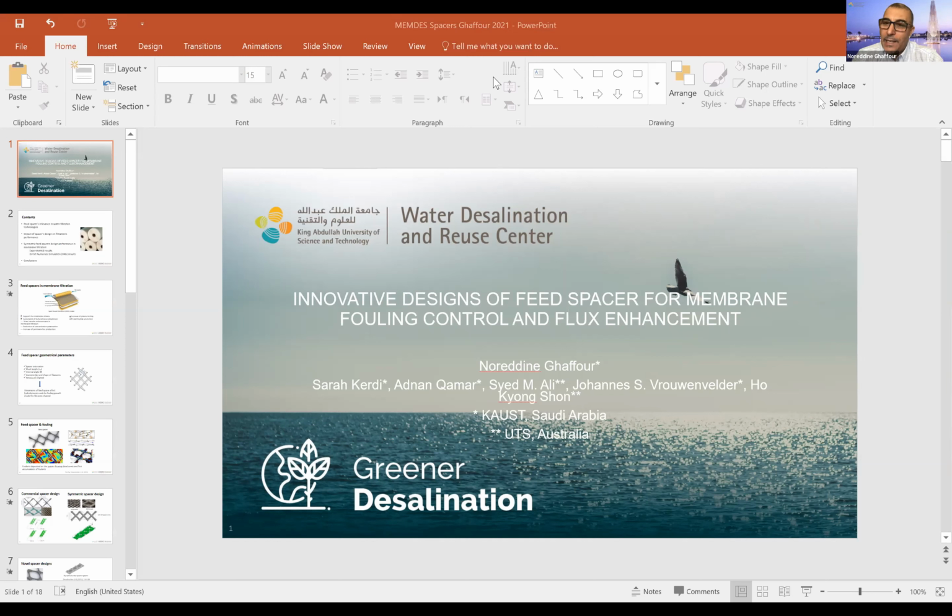I mean, we also contacted the membrane manufacturers. They actually want to reduce the thickness of the spacer instead of increasing it, while we know that thicker is better because you have more turbulence. But the pressure drop was also one critical point. But for the hole spacer, perforation is good because we can put holes. So I just suggest to see the papers. I put some references in this presentation, but I would be happy to share the results of the different thicknesses of the spacers we have used.